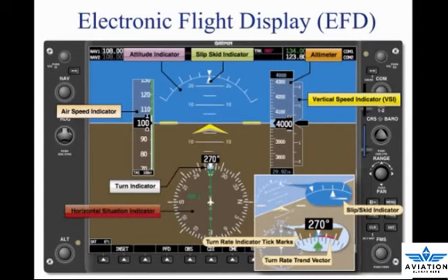The turn indicator takes a slightly different form than the traditional instrumentation. A sliding bar moves left and right below the triangle to indicate deflection from coordinated flight. Reference for coordinated flight comes from accelerometers contained in the AHRS unit. The slip skid indicator is the horizontal line below the roll pointer. Like a ball in a turn and slip indicator, a bar width off-center is equal to one ball width displacement.